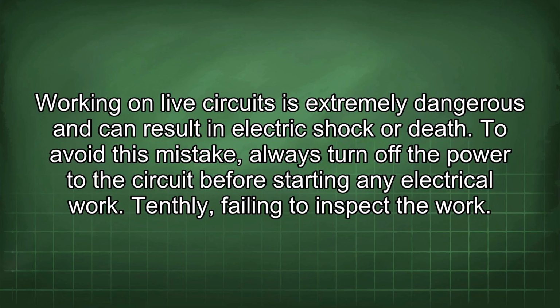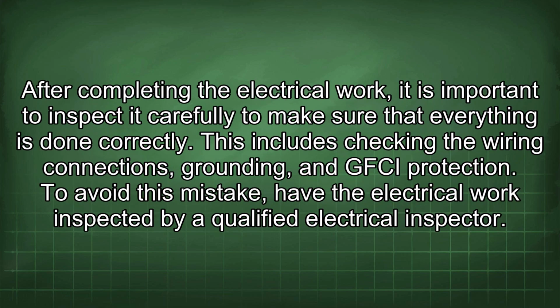Tenthly, failing to inspect the work. After completing the electrical work, it is important to inspect it carefully to make sure that everything is done correctly. This includes checking the wiring connections, grounding, and GFCI protection. To avoid this mistake, have the electrical work inspected by a qualified electrical inspector.